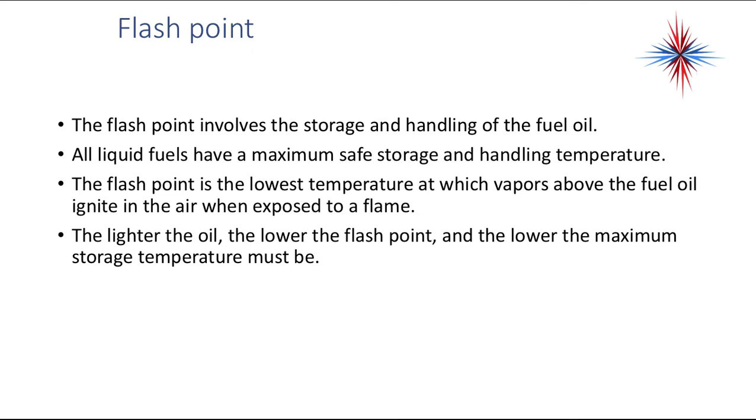The flash point is another such property. The flash point involves the storage and handling of fuel oil. All liquid fuels have a maximum safe storage and handling temperature. The flash point is the lowest temperature at which the vapors above the fuel oil ignite in the air when exposed to flame. The lighter the oil, the lower the flash point, and the lower the maximum storage temperature must be.